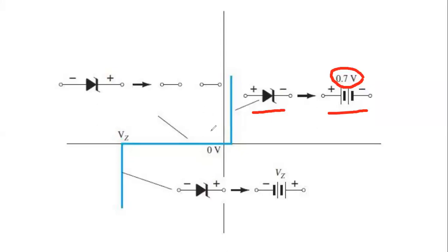But still, my students, I said that we have to come to this breakdown potential in the reverse bias condition. In the breakdown potential, the VZ, that is known as the Zener voltage, when the voltage across the diode reaches that point, at that time the Zener diode operates. So during this 0 to this region, the diode will be in reverse bias, something like we have done before. If we connect minus and plus here, that is the reverse bias condition, the diode will be open circuit. But when the voltage reaches VB, at that time a huge amount of current starts to flow.